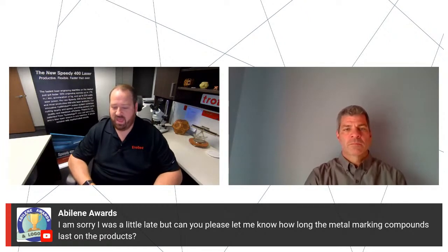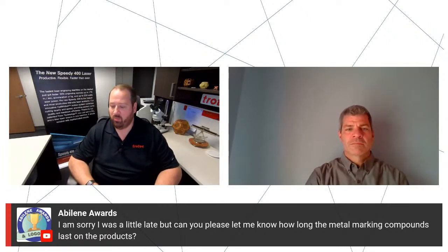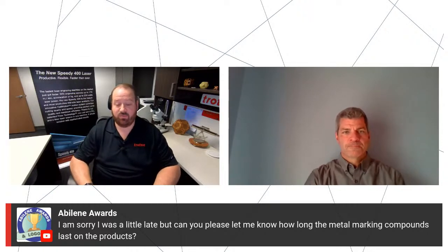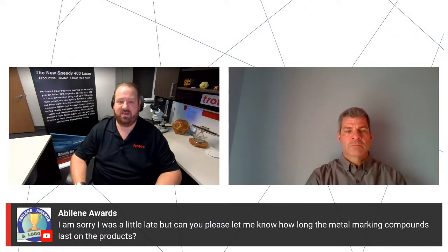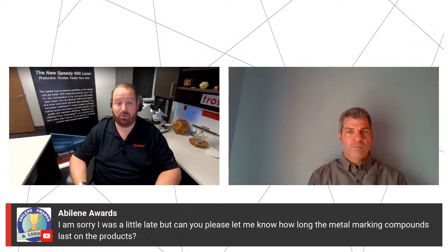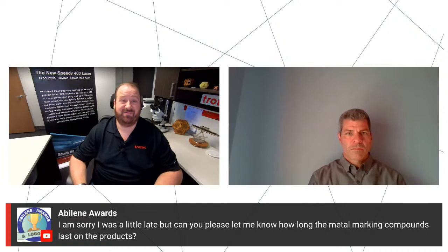Okay, I was a little bit late. Can you please let me know how long the metal marking compounds last on a product? That is a great question. I get that a lot. Metal marking compounds are an indefinite material. It is a glass fused metal. In the past, they tended to fade a little bit in UV, but later versions, about 10 years ago, became UV stable. They're going to last virtually indefinitely. So as long as the metal itself lasts, you should have a durable, permanent mark.